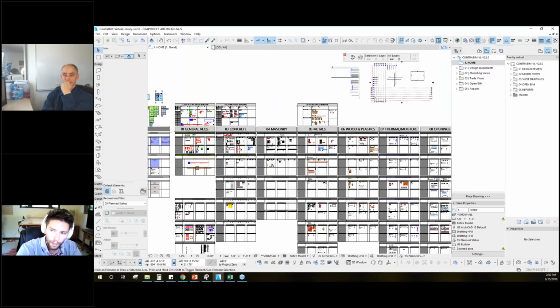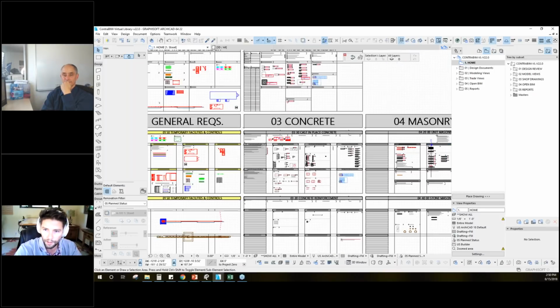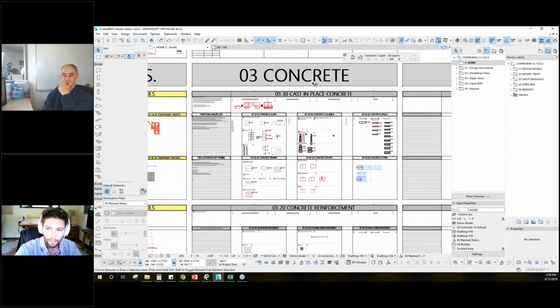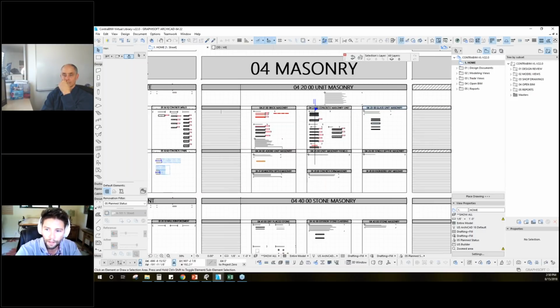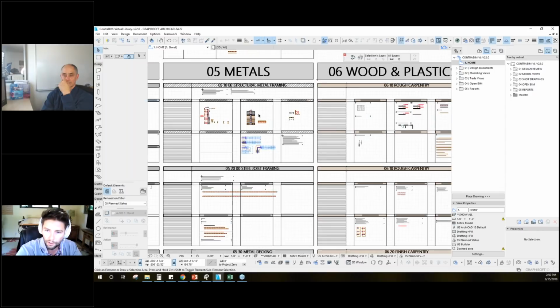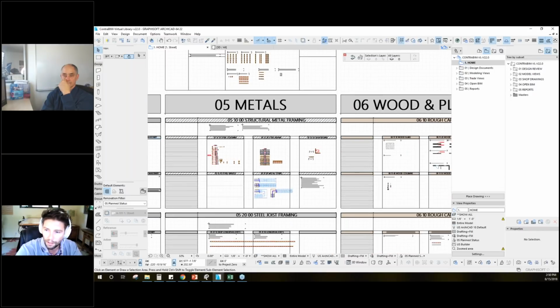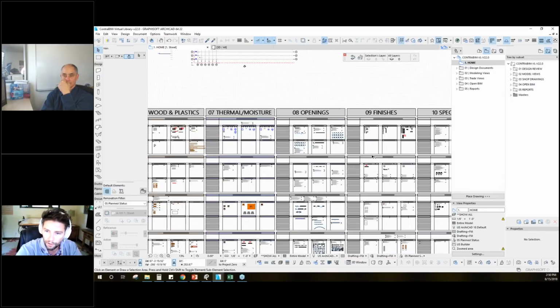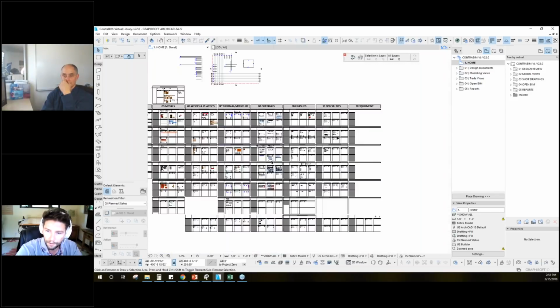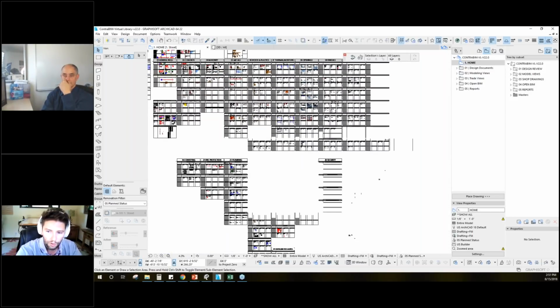So when I break off a new project, I'll essentially go through and delete all this stuff out, so I'm working with the base attributes. But the way that I organize my model favorites is all based on CSI format. And as you can see here, I have my standard model elements for all different types of systems, and really for every single trade of construction.